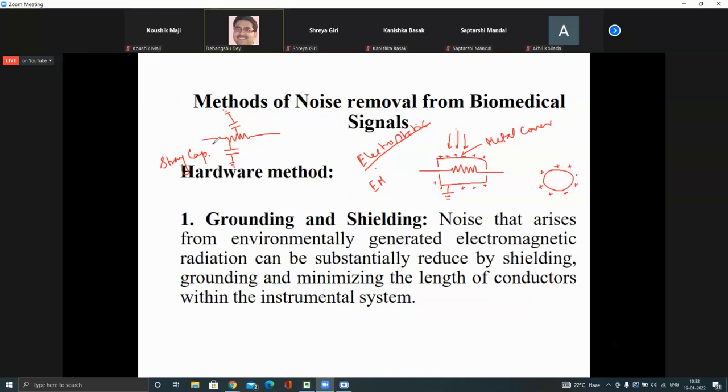And you know, at high frequency, those capacitor effects will be much more, because the impedance is 1 by omega C. So omega is high, the impedance will be low, so much more current will be drawn through these stray capacitors. So under AC, those stray capacitors you cannot eliminate. They will be there. And these stray capacitances will not be fixed. At different configurations, at different positions, this capacitance will be different, because C is, say, epsilon A by D, and D and A will be different in different positions. If you apply this kind of shielding, these stray capacitors, whatever they may be, their effect will no longer be different in different positions. This body is grounded, so the stray capacitors with respect to this metal, resistors, etc. will be the same, fixed. So there will be some effect, but the effect will be fixed, and can be predicted, eliminated or estimated.